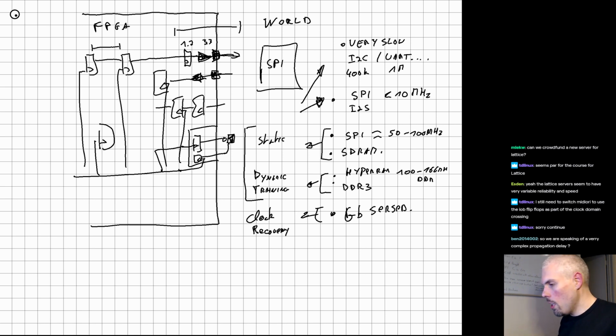So as I said, the other simplification we're going to take is that the FPGA and the registers and stuff like that all act symmetrically with respect to rising and falling edges. That's not the case. In practice, there can be some variation. Here, we're just going to ignore it, because it's relatively small, and if you take the average value between the two, you don't have that much deviation.